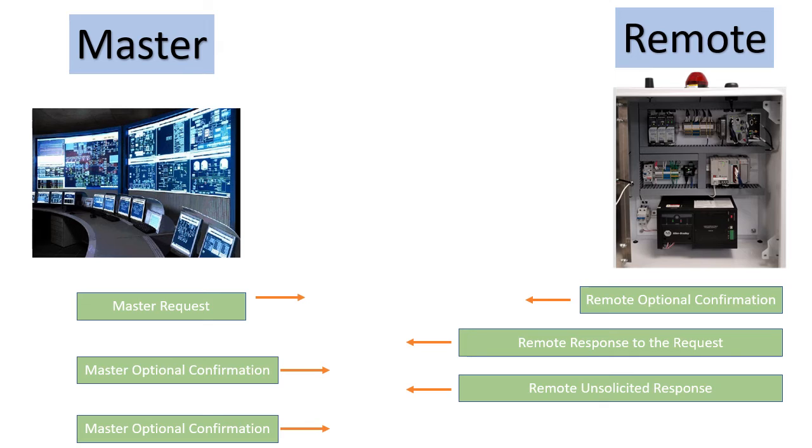This helps us to communicate faster, because normally this SCADA and the remote RTUs are placed along a pipeline, and the pipeline may range over a thousand kilometers, with a number of RTUs in between. Every RTU communicates to the master through polling, and maybe after 2 minutes or 5 minutes, the same remote gets a chance to send data to the master.